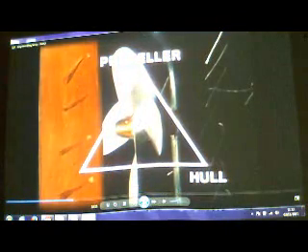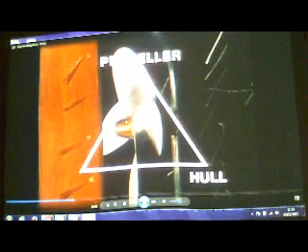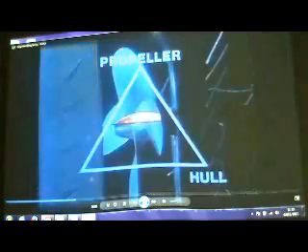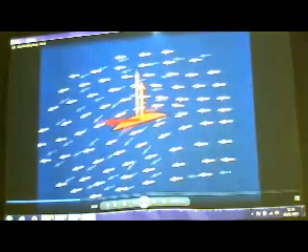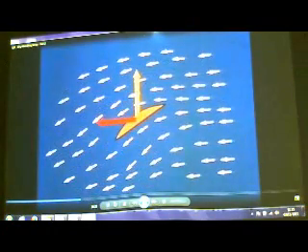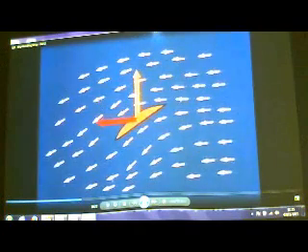What is the effect of interaction between propeller and hull? First, the basic hydrodynamics of the propeller blade moving through the water are explained. A cross-section of the propeller blade is shown moving through the water at a small angle of incidence. The blade will produce a drag, the red arrow, and a lift, the yellow arrow. At a greater angle of incidence, the lift and drag increase. The drag forces act in the plane of the propeller's rotation, and the lift acts parallel to the propeller shaft.